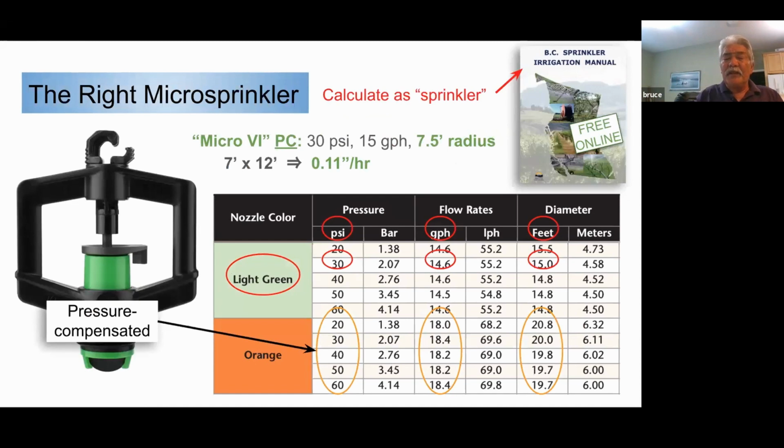Right, micro sprinkler. There is a place that starts to get confusing when you're looking at micro sprinklers, and they say, well, is this drip or is this micro? Is it a sprinkler? Well, when you're calculating out your flows, a micro sprinkler is a movable sprinkler that's throwing water around, emulating closer to that of a sprinkler head than a spray or drip would be doing. So we utilize the micro sprinkler booklet to determine how to calculate out the application rate.